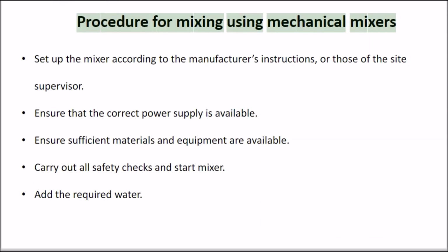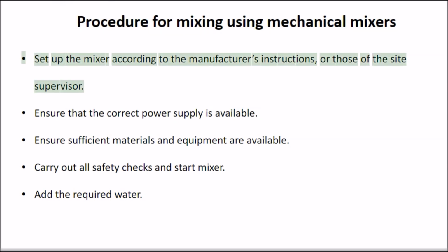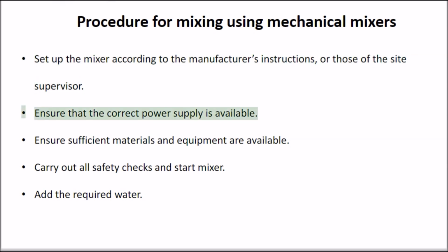Procedure for mixing using mechanical mixers. Set up the mixer according to the manufacturer's instructions, or those of the site supervisor. Ensure that the correct power supply is available. Ensure sufficient materials and equipment are available. Carry out all safety checks and start mixer. Add the required water.